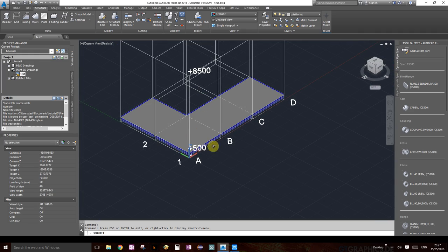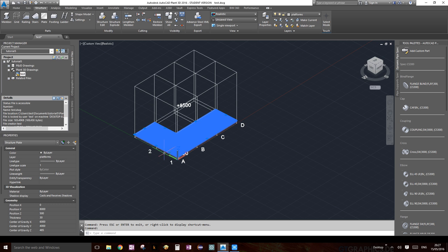Okay, so here is something I'll show you why using the properties window can be very beneficial. Now I actually want this to be at the very top. I don't really want it at the bottom, because I wanted this area that I'm indicating here actually open. I want this to be at the top. So how can I do this? Once you have selected the grading, the entire grading as an object, the properties window shows, whatever is selected on the model space or paper space, all the properties that are specific to that object or that group of objects.